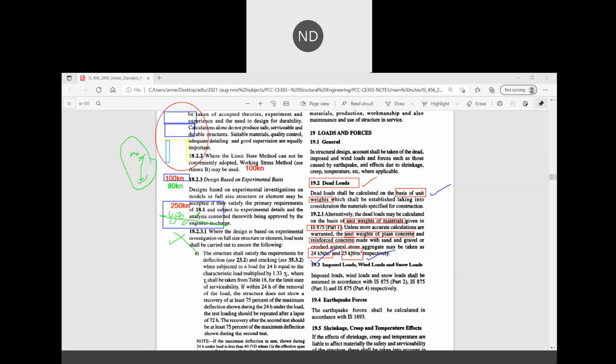In pre-stress you have steel tendons used. Those precast members are used in your bridge. Sometimes the bottom portion of the bridge is made of concrete and the upper portion is made of steel. Sometimes the bottom is steel and the upper one is concrete, in some cases. So that's why I said, wherever you need to calculate the dead load of any structural member, irrespective of only steel. If it is only steel, obviously you're not going to use the concrete one. Wherever concrete comes, and that member has concrete in it, you need to find out the dead load. But steel plus concrete, then you need to know that particular concrete's weight, okay?